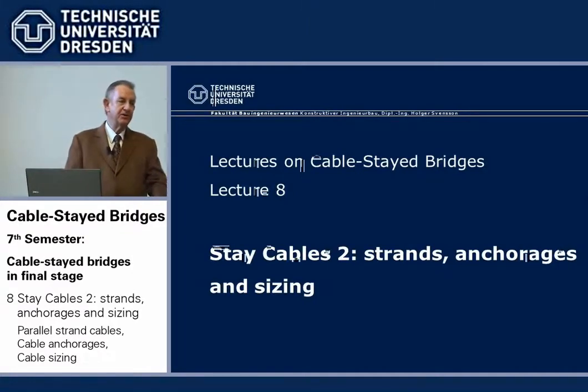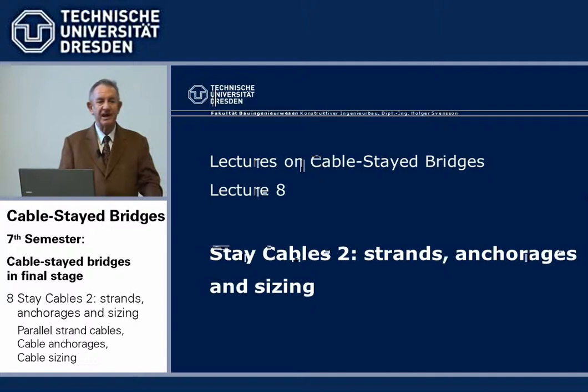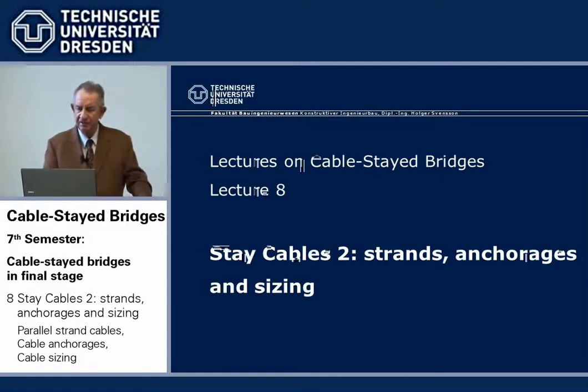We come to the second part of the lectures on stay cables, where we deal with the third of the three important, and in itself maybe today the most important type of stay cable, that's parallel strand cable. And then we will go a little bit into the anchorages of stay cables in general, tower and beam. And we'll talk a little bit about the sizing, how we calculate the diameter of these stay cables.